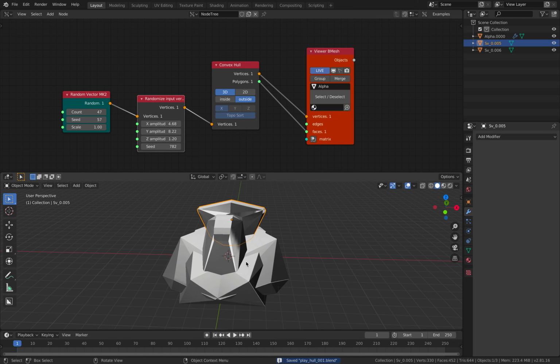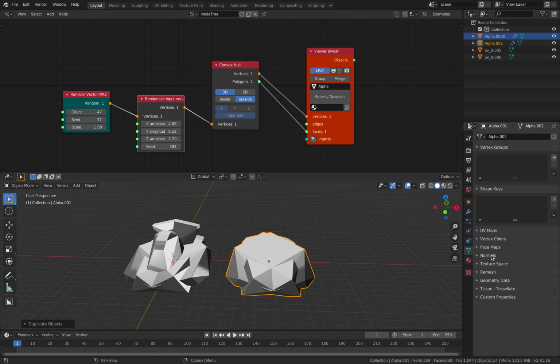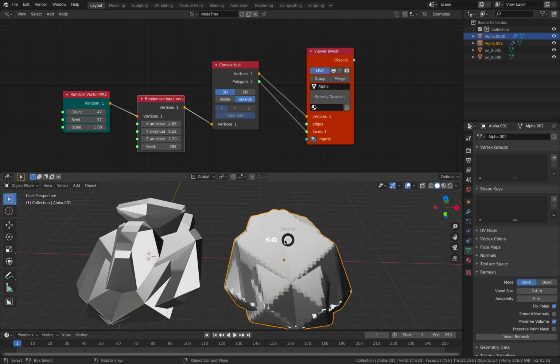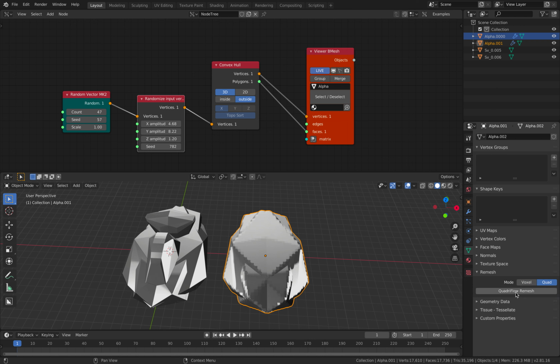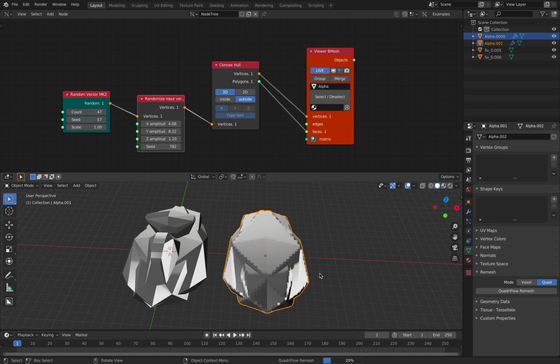If you're happy with the shapes, you can actually just use the remesh, voxel or quad. Five voxel remesh, and this becomes a cleaner surface than before. There's even quadriflow. Okay, that's interesting that it's added in. Okay, that doesn't keep the shapes, but it's actually not too bad.